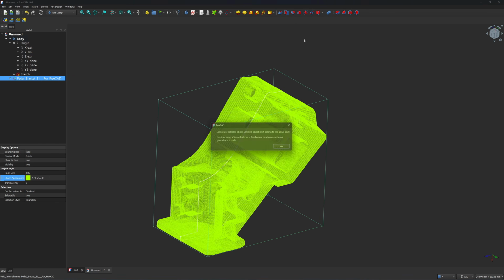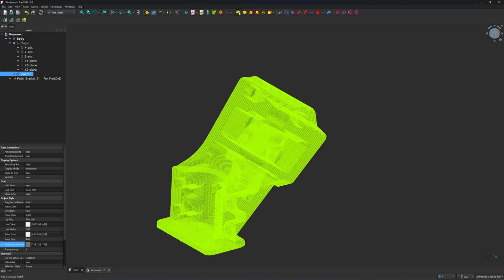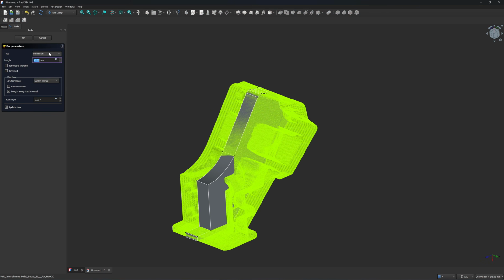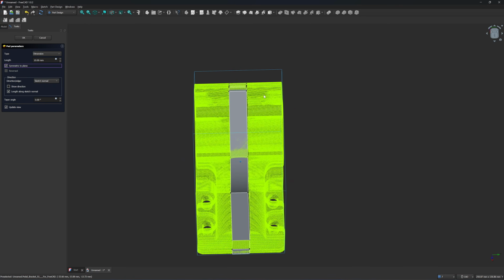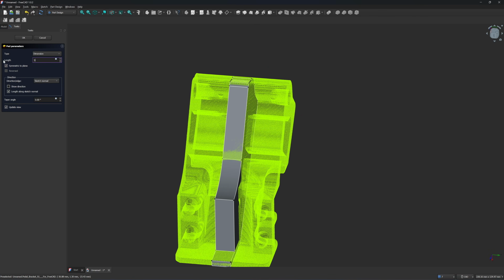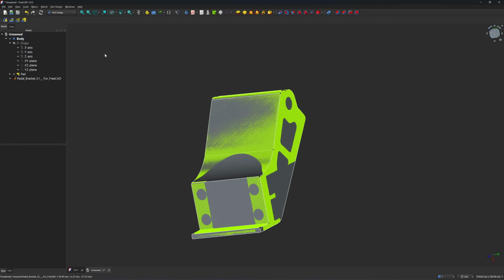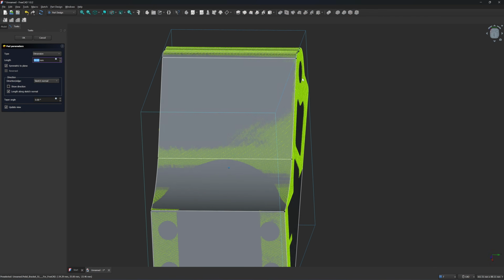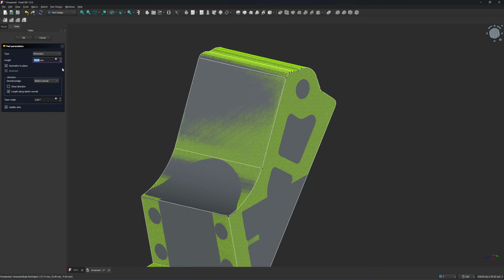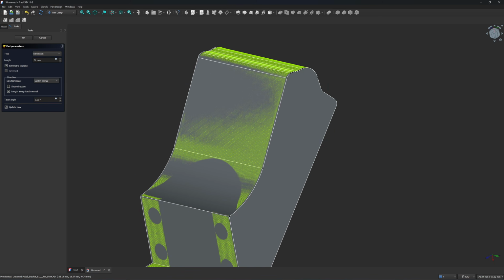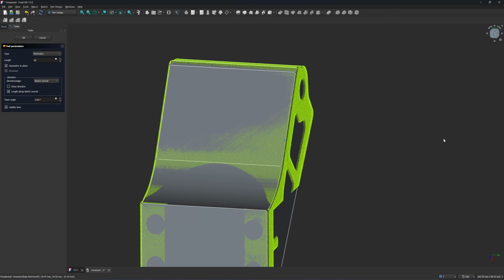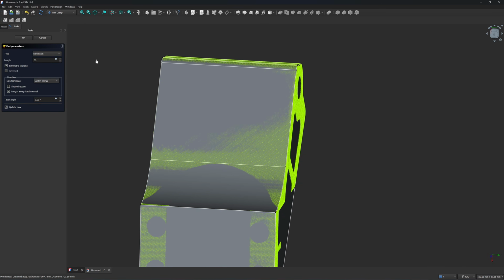Next, I'm going to click on the Pad command. Click on the sketch Pad command, and I'm going to click on symmetric to plane because I'm going to extrude on both sides, and for the size, let's try 50. Now if I use 50, it's going to touch the point cloud here. This is its dimension. You can try 51, it's too wide, or 49, it will be too much. You can see it when it touches the point cloud. So 50 is the number.